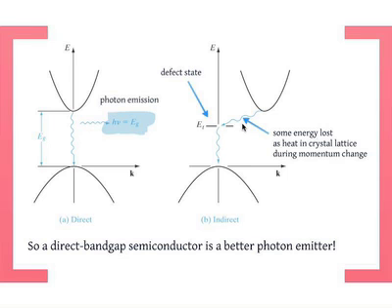And for silicon, there tends to be some advantages because sometimes you do not want thermally excited electrons to reach the conduction band. For instance, a simple example is if you have a transistor made of silicon, if thermally excited electrons get into the conduction band, they can open a switch, close a switch. Let's say a switch is open, and if you just have some ambient heat, electrons get in there, it can close the switch. And that's a problem, right? That will be noise in your transistor. We'll see this later on.